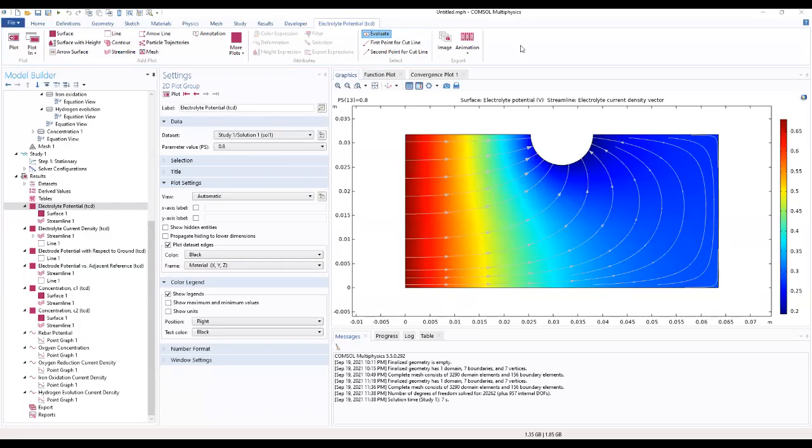In this section, we'll be looking at cathodic protection in concrete. We'll build a model in 2D, and we should produce results for the current density for hydrogen evolution, iron oxidation, oxygen reduction, and also make a plot of the oxygen concentration over different values of pore saturation.